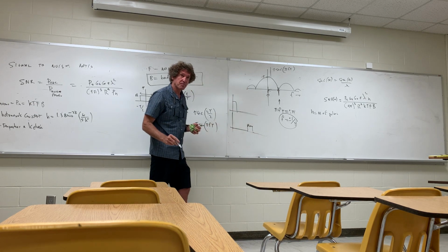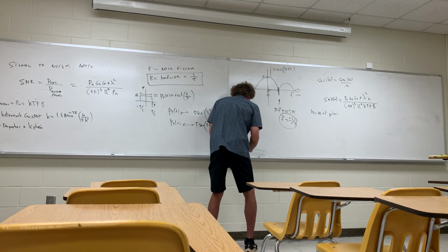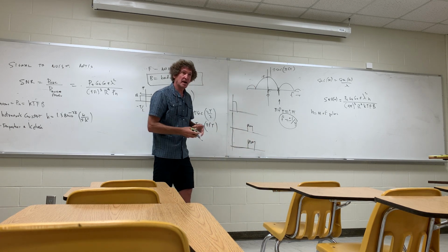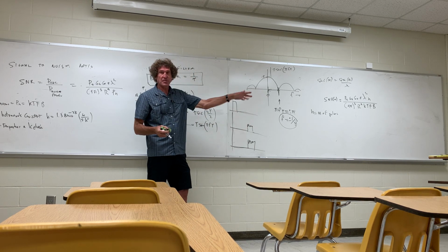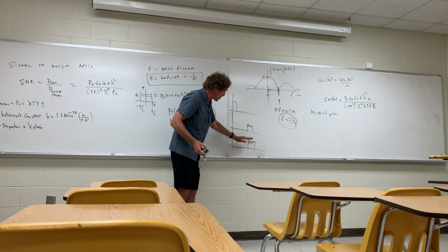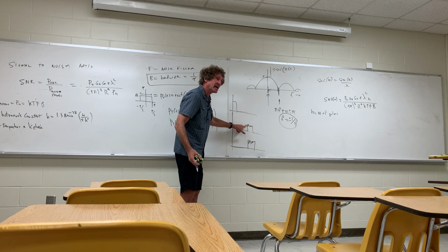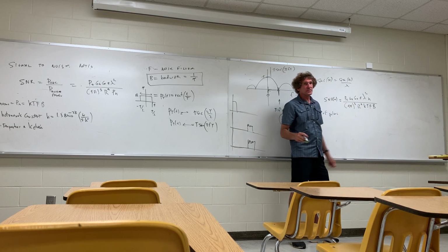That's one pulse. Now I send another pulse. Get the same basic thing. I'm going to have the same time delay, and what I get back would be this. This would be pulse 2. So it's got noise and the signal. Follow me? And then I send a third pulse. But when I add all these pulses that I receive, then mathematically, using digital signal processing, I would add them. The noise doesn't add, just the signal, follow me? And that's why the number of pulses is so important.